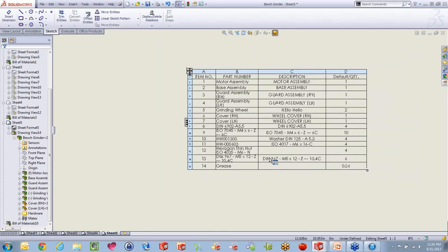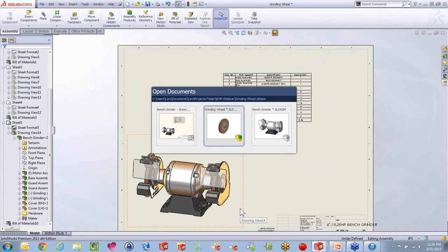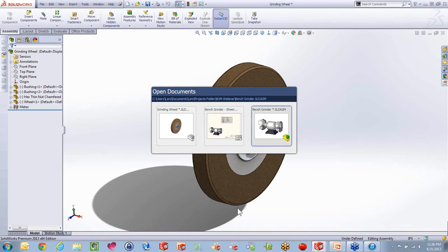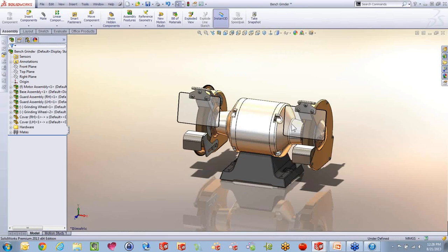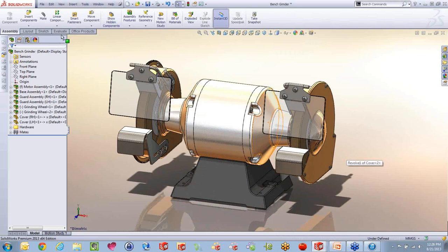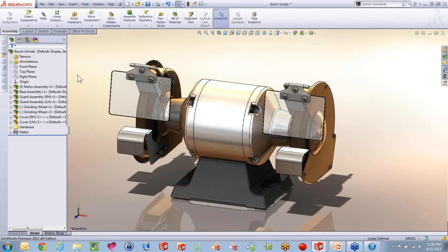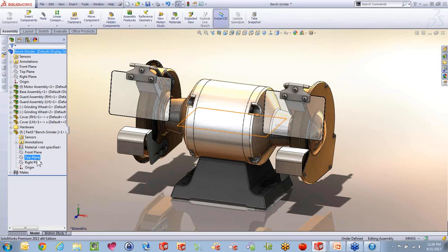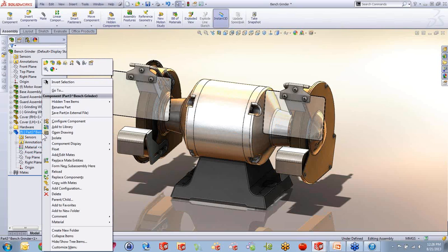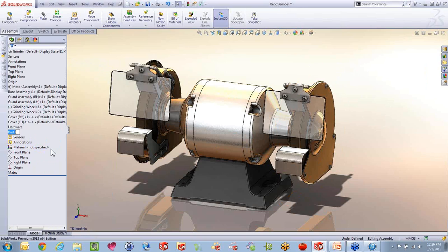Another thing that some of our customers do for that is actually insert it as a virtual component. And if you don't know what a virtual component is, that is when we insert a part inside of an assembly without starting from inside the assembly. The way you can do that is if I go in here and I say insert a new part, and this is just going to insert a new part inside my assembly. There is nothing inside this part. And now again, I can right click, I can rename it, and I could call that grease 1.